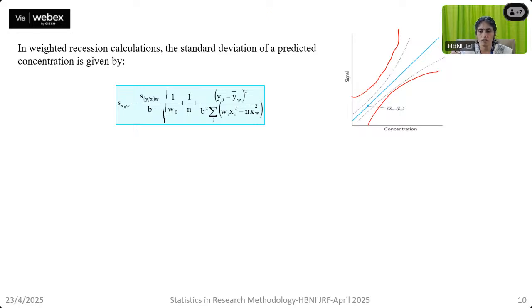Whereas when we do apply the weighted regression, you can visibly see that the confidence interval becomes narrower at lower input variables as a function of the magnitude of the variation at the lower concentration range. So as and when we utilize instruments for measuring lower signals, where the instrument output is giving us the freedom to reduce the interval, we should judiciously utilize it and come out with better quality data, wherein this weighted regression has got importance. That is what is conveyed over here.